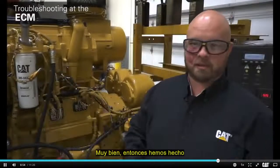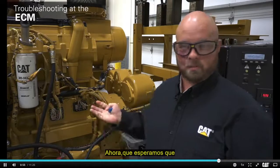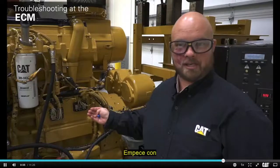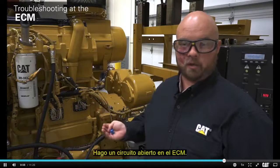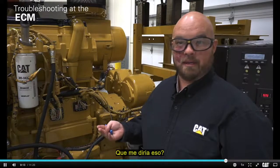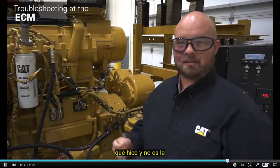All right, so we've made our open circuit condition. Now, what do we expect the ECM to do at this point? If we create an open circuit condition, I would expect to see a -3 voltage above normal code. So if that happens, I started out with a -4 voltage below normal. I make an open circuit at the ECM. If the code then changes, what would that tell me? The ECM is recognizing the change that I made, and it is not the source of the problem.